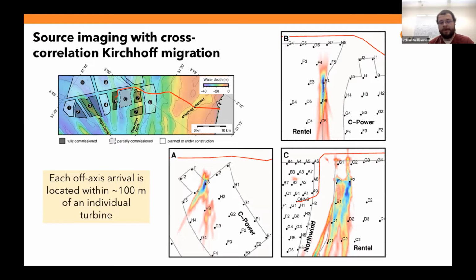And so, for example, different types of surface waves are generated by torsion versus rocking versus shear of the foundation. And so there's a lot of potential here that we haven't developed yet to quantitatively figure out, for example, the ratio of Scholte to Love waves as a function of the type of motion of the foundation, which could be impactful, for example, in monitoring scour impacting the foundation of an offshore wind turbine on an ocean bottom, where that's a concern for structural integrity.